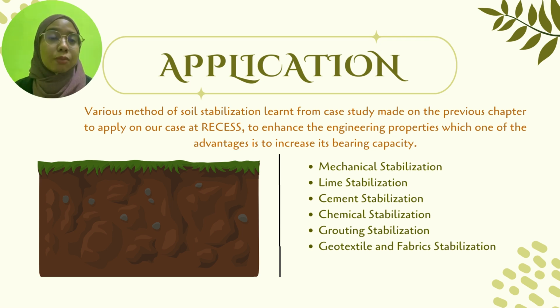So now we're going to move to which method for soil stabilization in order to support the pavement and also the foundation. Before we begin, I need to explain what soil stabilization is. Soil stabilization is a process of altering the physical properties of soil, and it can increase the shear strength and also control the shrink-swell property of soil, thus improving the load bearing capacity of subgrade.